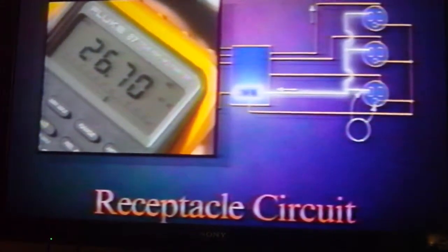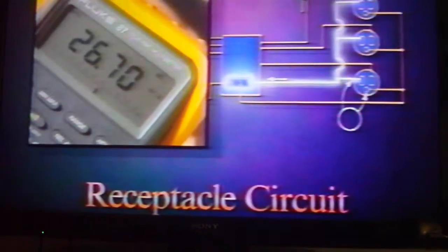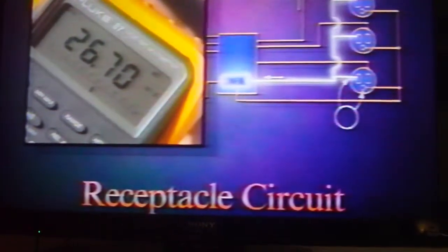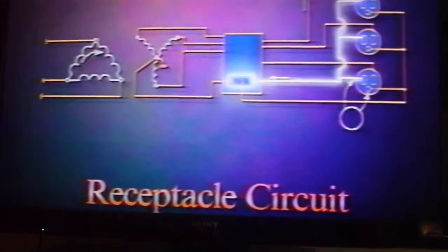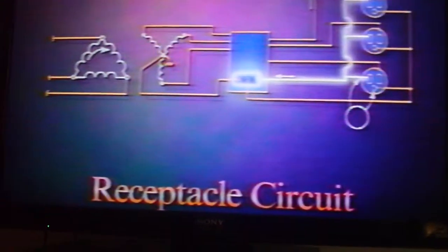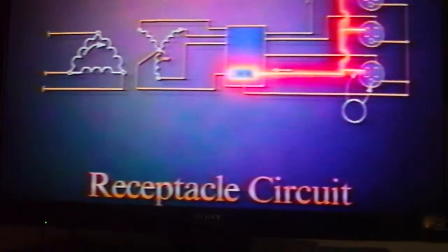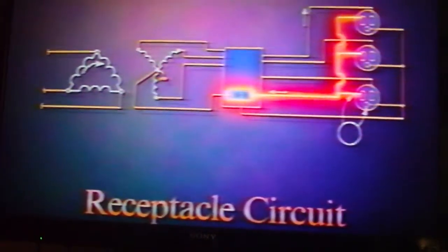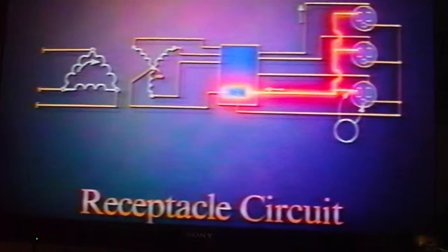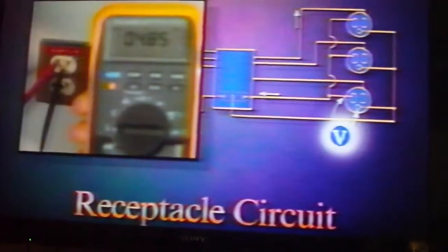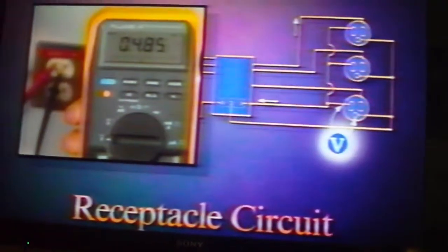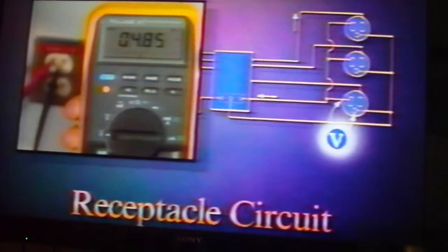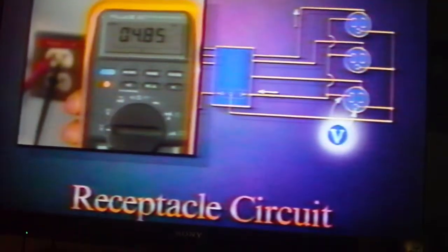This neutral current can typically be 130% of the total current measured in any individual phase. This situation is worse if neutrals are downsized. Again, the danger is overheating because there's no circuit breaker to limit the current in the neutral conductor. Excessive current in the neutral conductor can also cause higher than normal voltage drops between neutral and ground at outlets.